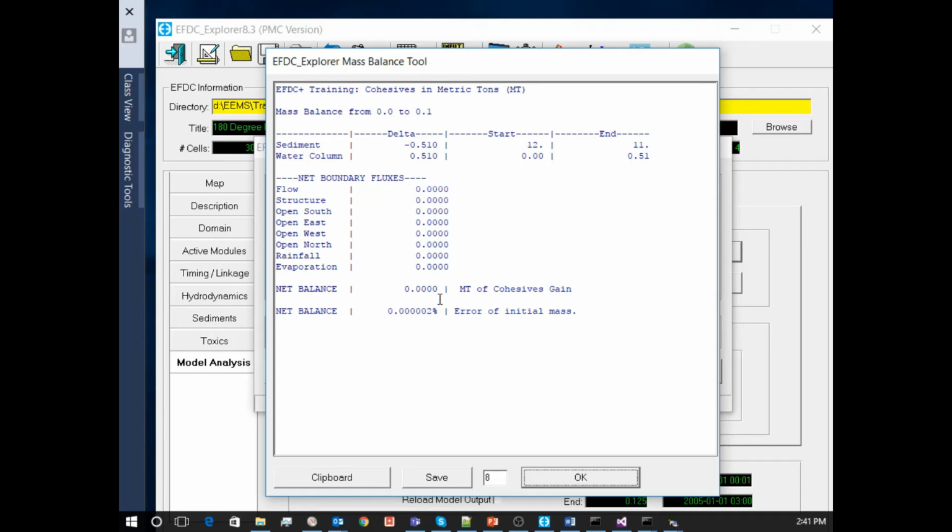Now the model will produce a zero mass balance if everything's good in the code, but you may be drying out the reservoir because there's truly not a balance between the actual inflows and outflows relative to the volume of the reservoir. That's kind of a different problem.